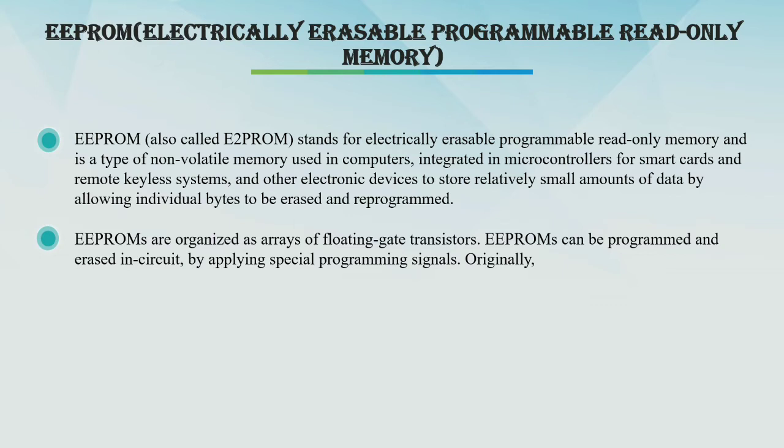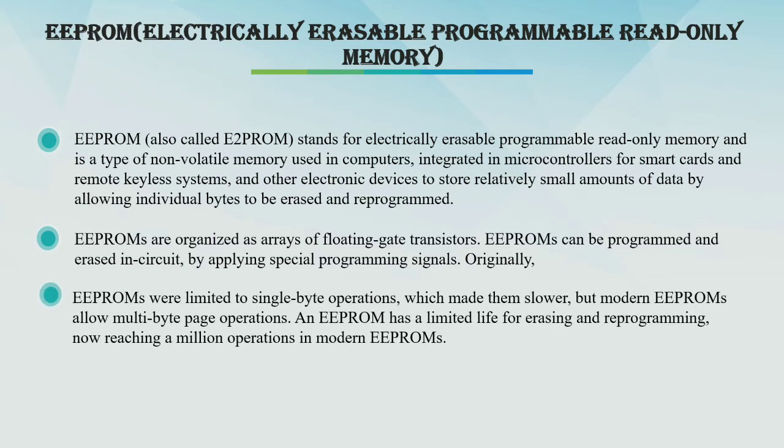Originally, EEPROMs were limited to single byte operations, which made them slower, but modern EEPROMs allow multi-byte page operations. An EEPROM has a limited life for erasing and reprogramming, now reaching 1,000,000 operations in modern EEPROMs. These are the images of EEPROMs.